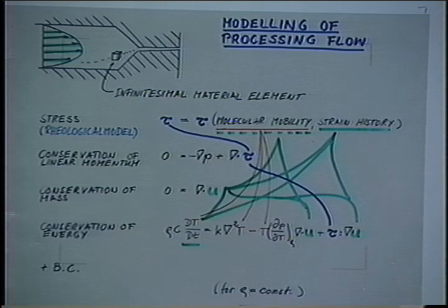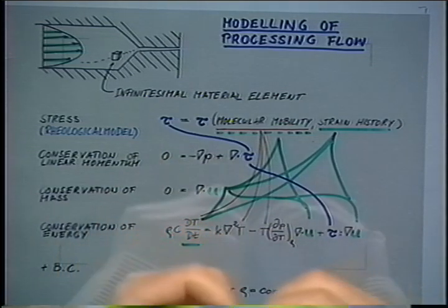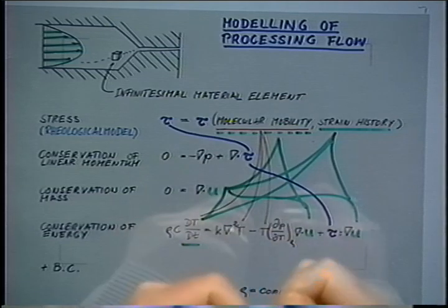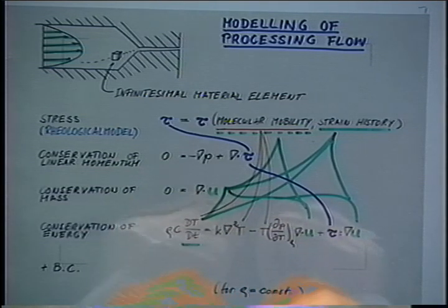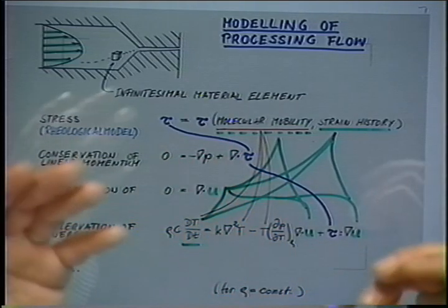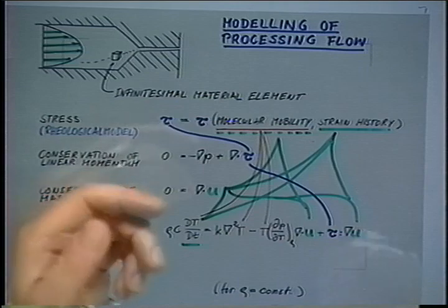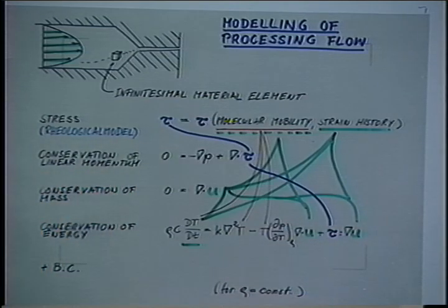And that's the phenomenon which you would experience when you take a metal paper clip and bend it back and forth. You're deforming a paper clip. And in the range where you're bending this paper clip, you will see that the paper clip is heating up. What you would do in that experiment is you would convert the energy which you put in by bending the paper clip into internal energy, motion of molecules of the metal the paper clip is made of. And the same thing happens in polymeric materials. The stresses are often high. The rates of deformation are high. So there would be some temperature change due to that viscous dissipation term. And this term would be the energy per unit volume and unit time occurring in the system. Okay, so that's the blue term.